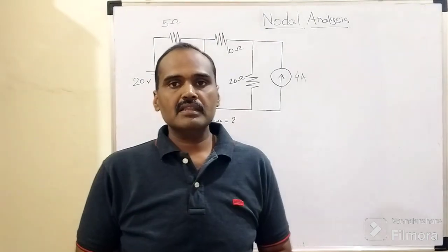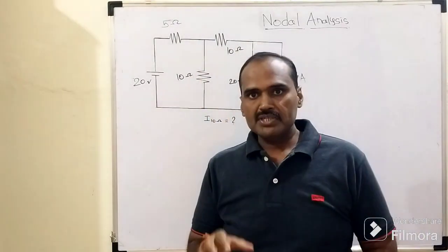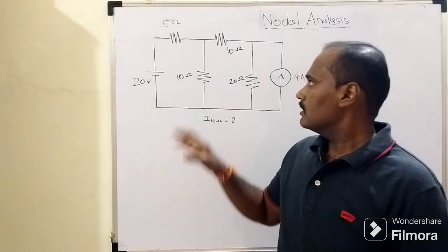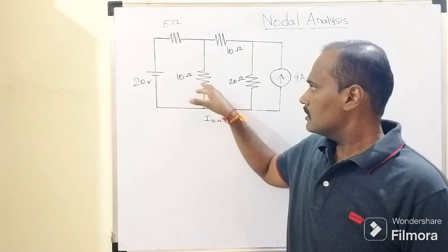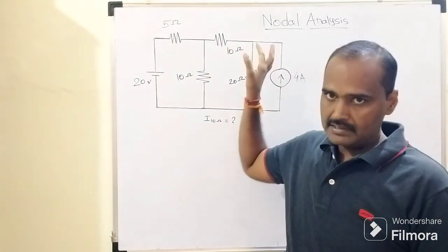So friends, in this session we will try to learn another circuit analysis technique, whose name is nothing but the nodal analysis. As you can see, the objective for today's session is to determine the current flowing through this 10 ohm resistor by using the nodal analysis, right?